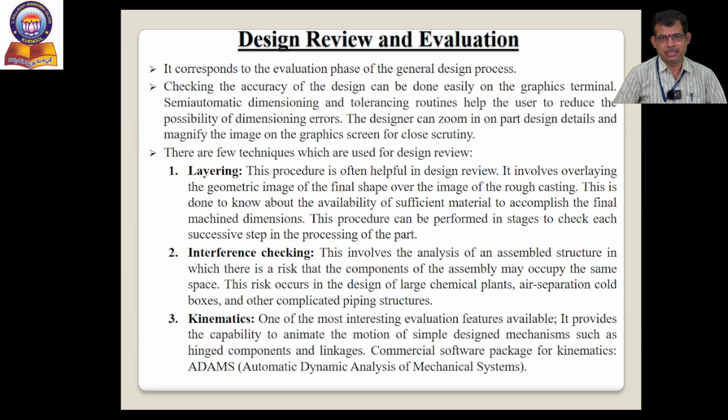Then the kinematic analysis. One of the most interesting evaluation features available in the design review and evaluation of the CAD process is kinematic analysis. It provides the capability to animate the motion of simple design mechanisms such as hinged components and linkages. When the animation is going, you can very easily understand what is happening, whether it is moving exactly or not, and whether any overlapping, coincidence, or collapsing is there.